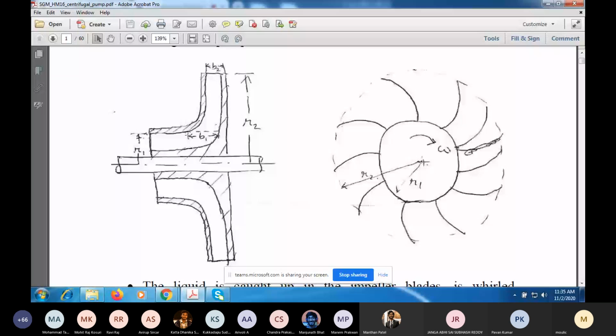Suppose you have a viscous fluid in a circular pipe, and the pipe rotates about its own axis. Then the V theta for a fluid particle sitting on the surface of the pipe will be non-zero. The no-slip condition states that V theta will be the radius of the pipe times the angular speed.